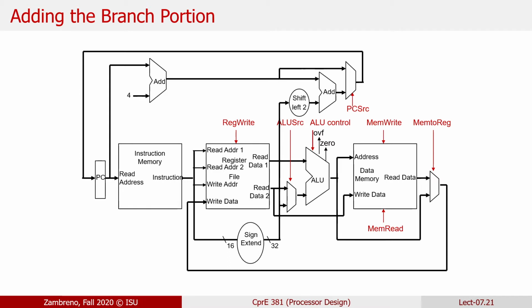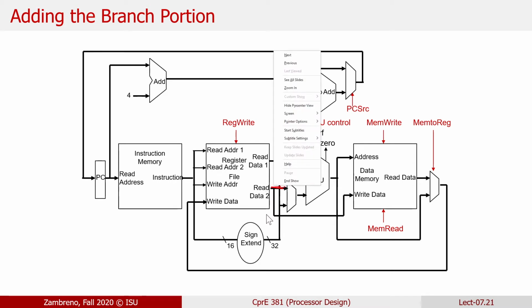There are many such examples of it just on this diagram itself, but one way you can consider that would be to look at, for example, the second input to the ALU and realize, well, I have both potentially the register value that I want to actually connect, and I have the actual immediate input that I want to connect in, and that's why I have that mux there.